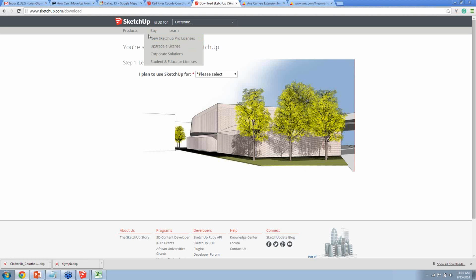So you can import CAD files. But the same way, you can export DWGs and DXFs from SketchUp. So that means that in theory, you can do work in SketchUp and export that, and then the architect or engineer can reincorporate that into a floor plan.